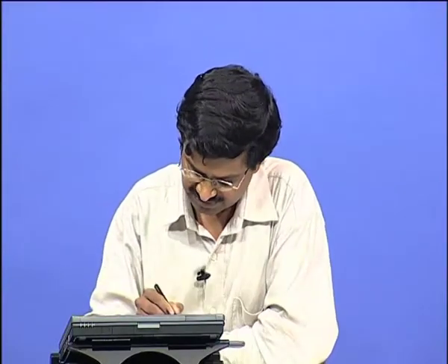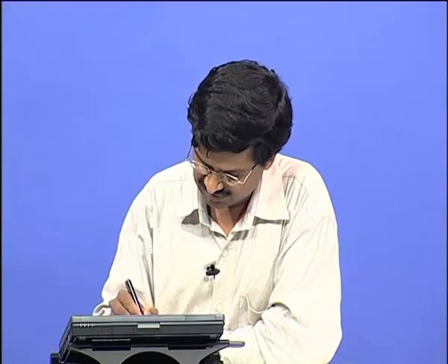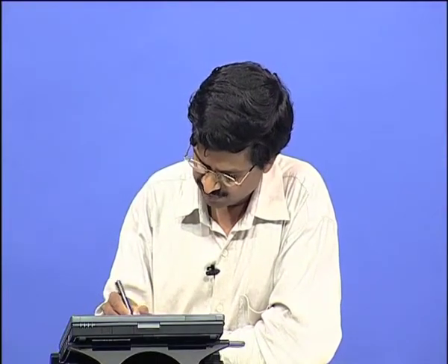Even with your hand you can try on a flat surface of water in a tank. When you move slowly, it will be less force. If you try to move fast, it will drag more, that is called drag. Ships and boats experience the same thing in water. That is apparent in our relationship, where the shear stress is proportional to the velocity. So, the shear force is a damping force, and we have to multiply tau by the area of cross section.